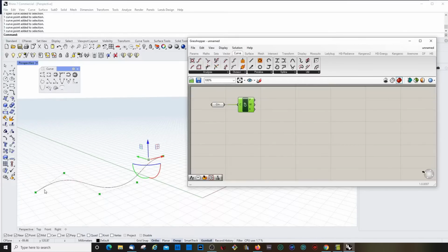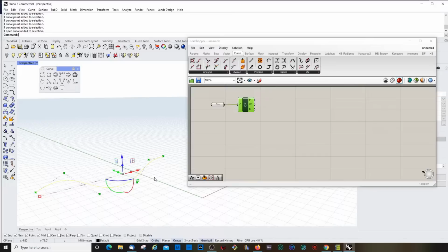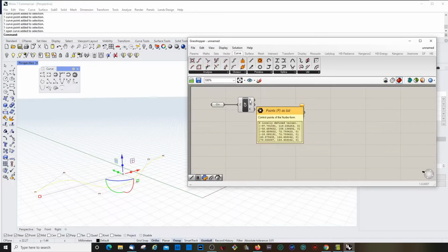And then I want to draw vertical lines on these points. I want to keep them on these points, meaning if I change my curve within Rhino, these lines update as well. So how to do that? I take my line tool. We saw that before, I think. And the line is defined by a start point and an end point. And I can say, these are my start points. And to make a vertical line, I just copy these points and move them in the set direction.